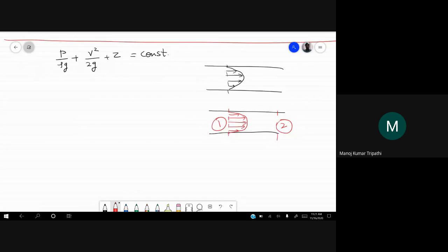then the kinetic energy, because this is an energy conservation equation, we are saying that the energy because of pressure, the energy because of the kinetic, the movement of the fluid, the kinetic energy, and the potential energy, that remains conserved from the first section to the second. So if the velocity is same at all the points in a cross section, then we can take any velocity here.